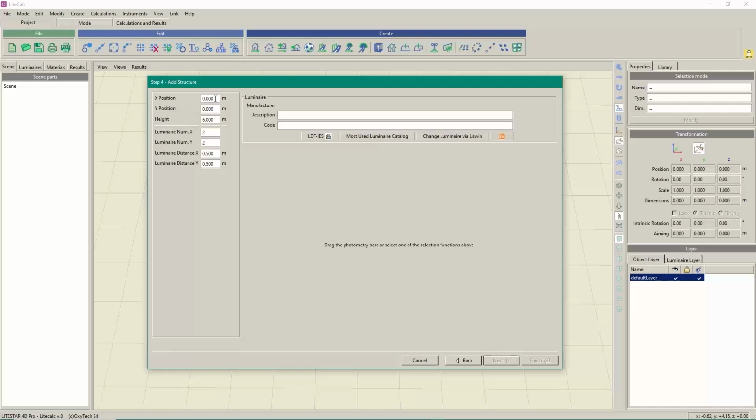So let's define the position of the high mast. In this case, we place it at minus 55, minus 45 at a height of, let's say, 25 meters. And we do not create a panel with many luminaires. My approach is to show you in a very simple way, with few luminaires, how the program works.